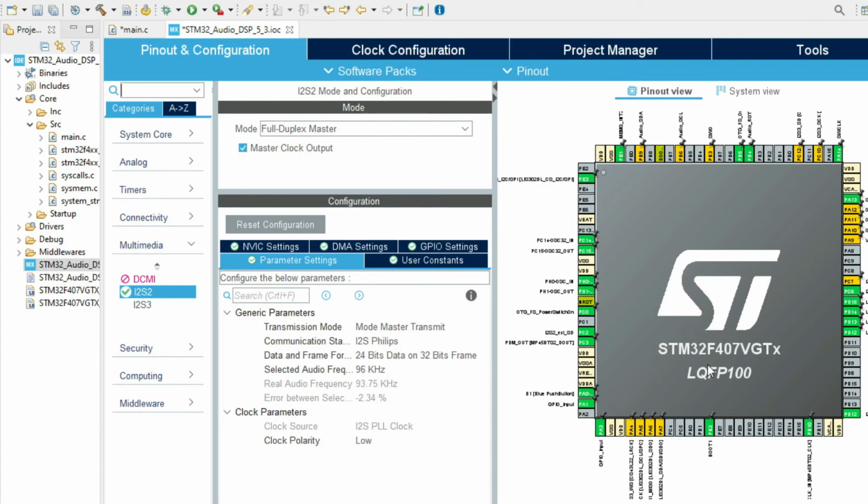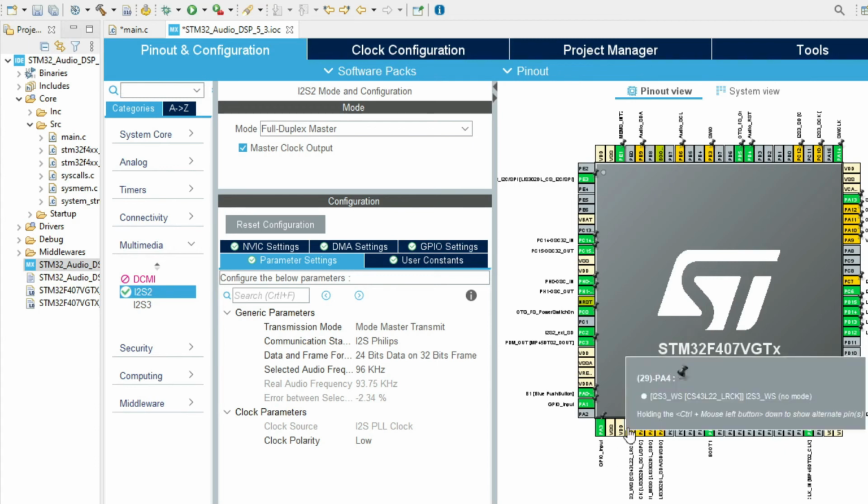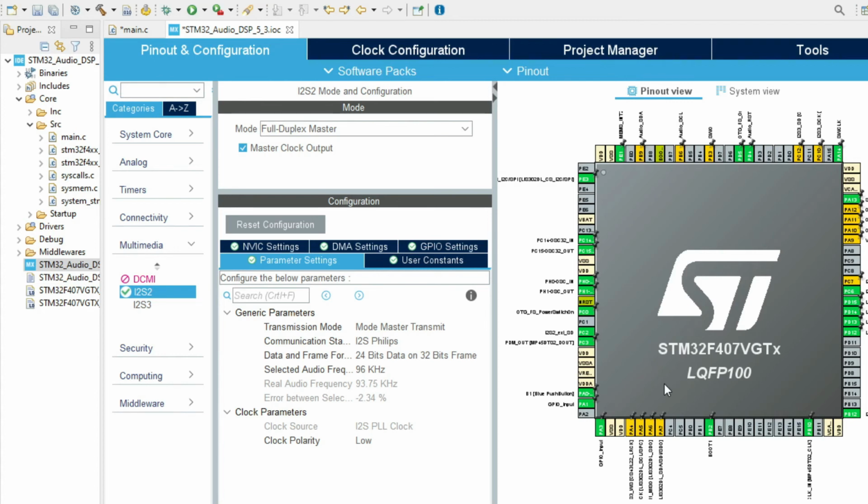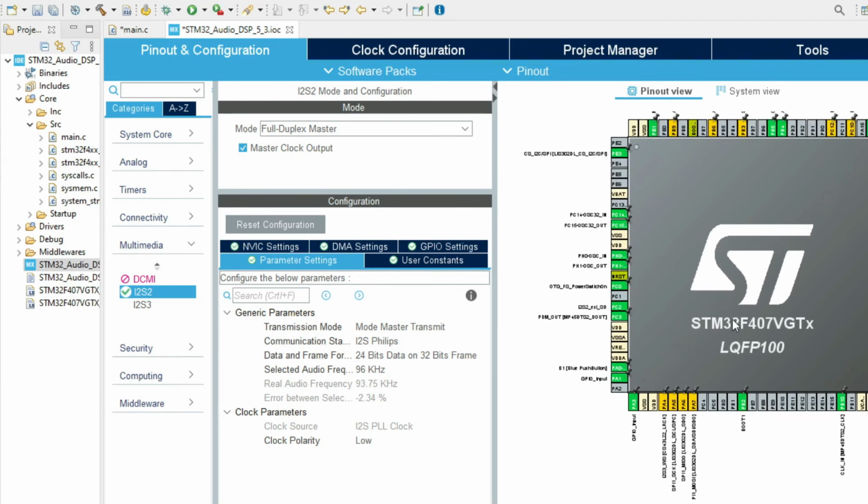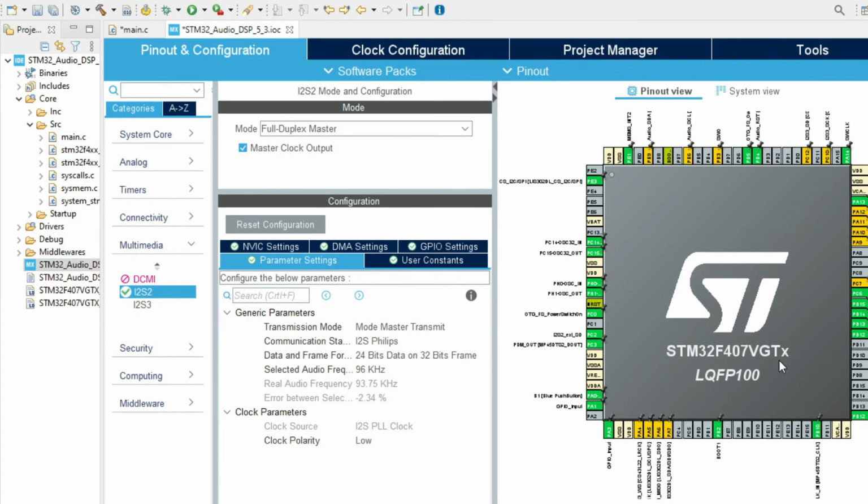And within this initialization code, you can go ahead and start your application. And whenever you go back and see, oh, I need another pin as an input or an output, you always can go back, change that, and go back to your initialization code. And it's properly separated your user-defined code and initialization code. And so it's a very powerful, very nice tool. You're very fast setting up your microcontroller and get up and running.